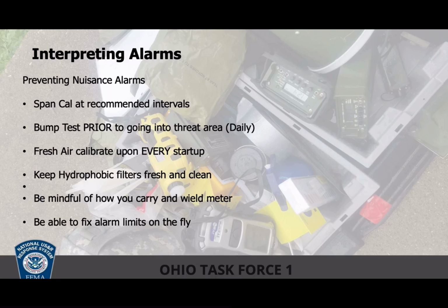Every manufacturer recommends bump testing prior to going to a suspected or known threat area. Usually, operationally, we just do that every day because most people don't carry cal gas on their apparatus, so it's easy to do at the fire station so that we don't have to do it when we go downrange. If you want to bump test when you go to perform work, you'd have to keep your cal gas with the meter, and logistically that's difficult for many departments.